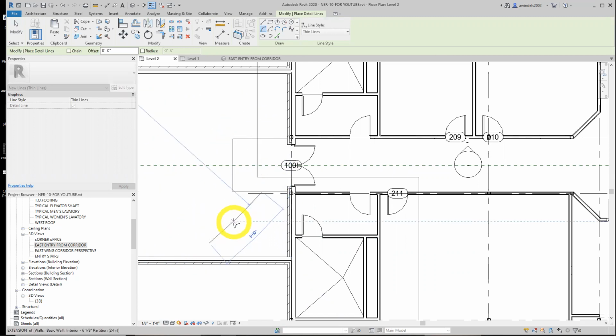And now for the radius, it's kind of confusing what they say. They just want it to go out here. So it's 90 degrees. It'll lock in. You'll see your hash lines. If you went this way, it'd be the same deal. It's going to be a really odd dimension radius, but that's okay. That's what we want. We want to lock in at tangent to the landing, or 90 degrees to the landing. That's what tangent means. Left click.